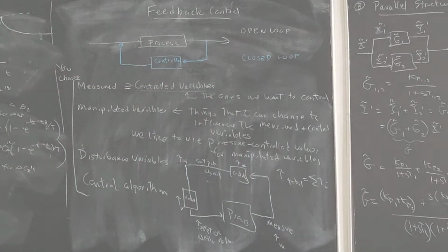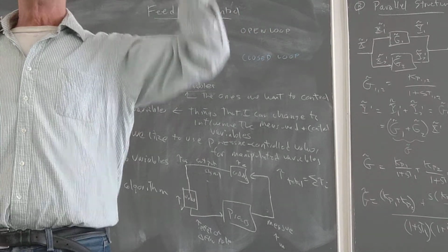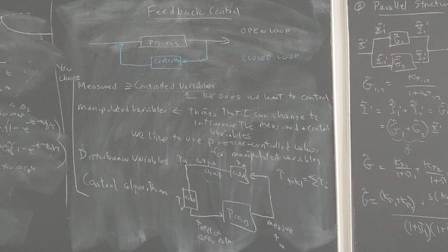And that's the important tau, because when I measure something wrong, I want to have an effect. And if it takes too long, then I have those delays, which I had up there, e to the minus s theta i. And what we find is that the longer the delays, the less stable the system is.